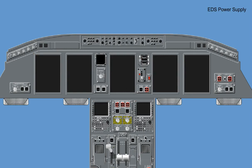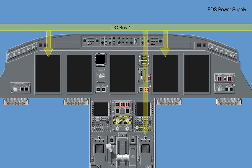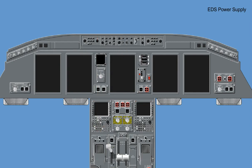All of the components require 28-volt DC power. The pilot's PFD, the co-pilot's MFD, the co-pilot's CCD, the pilot MCDU, and co-pilot's display controller are powered by DC bus 1. The co-pilot's PFD is powered by DC bus 2. The pilot's MFD and CCD and the co-pilot's MCDU are powered by the DC essential bus 2. The ICAS is powered by the DC essential bus 1. The pilot's display controller is powered by DC essential bus 2 via SPDA2.